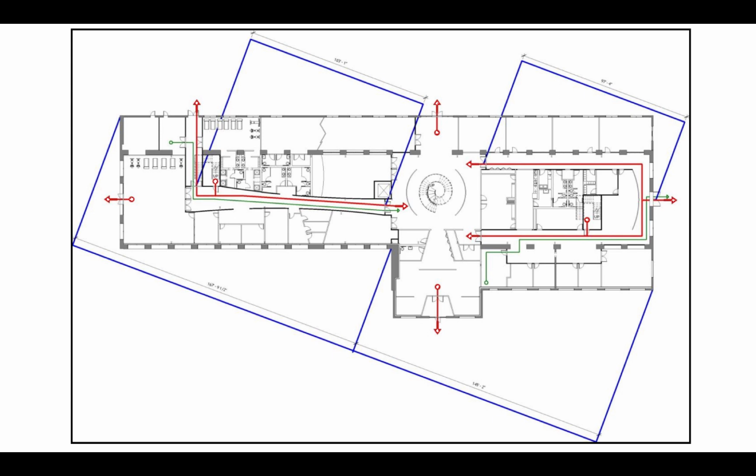The central wing of the building is actually a fire separation wall. That's basically a separate building. And the red lines, I believe, are actually measuring the actual distance you'd have to travel from one exit to the other. So if there was a fire in front of one door, you could run to the other door. As long as that's less than half the distance of the diagonal, you're good. Or 1/3 if you have sprinklers. And then the green line, I believe, although I think I must have cropped off the key, the green line is the maximum length of travel.